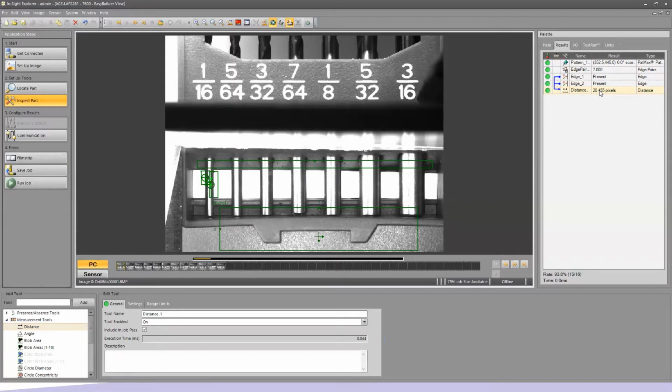We need to teach the camera how large a pixel is. So we need to calibrate it to a series of real-world measurements. Now, in the real world, we typically recommend using a calibration grid, but for the purpose of the emulator, we're going to have to use a feature that already exists within our image. So here's how we do that.